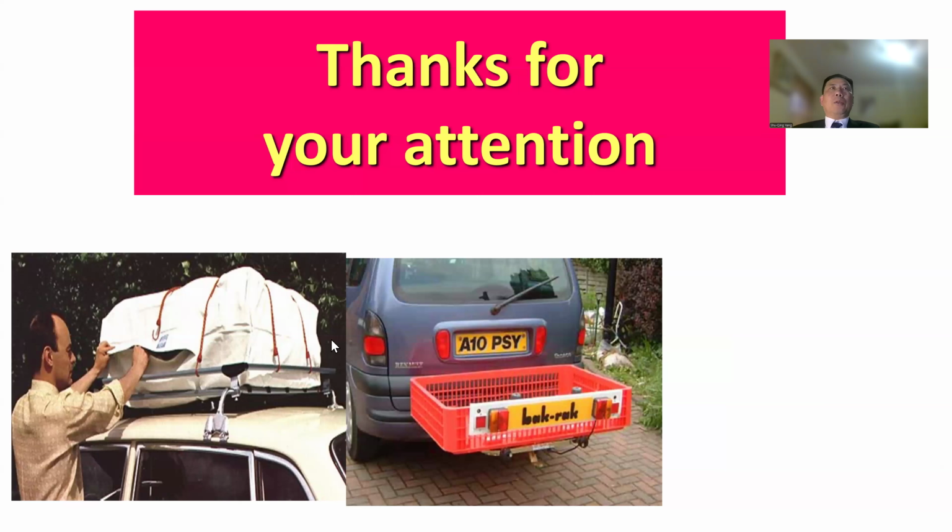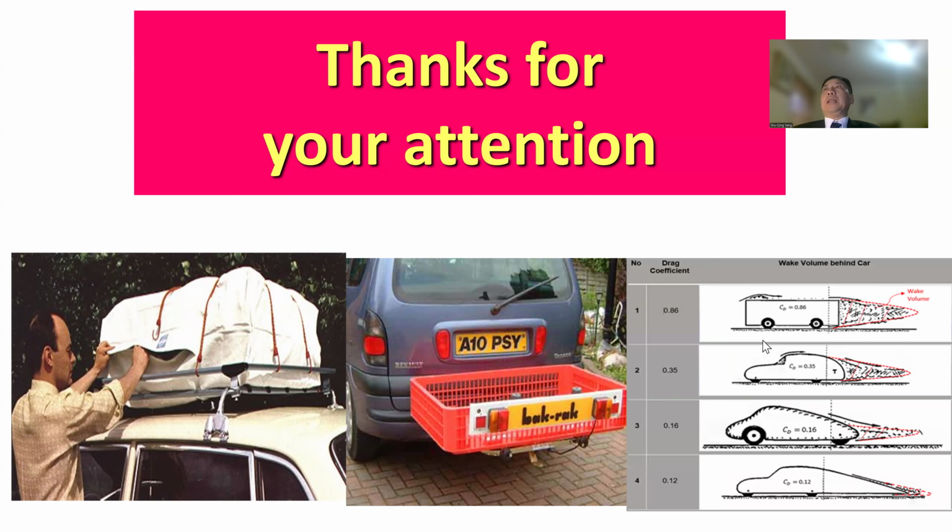And then I recommend you do an experiment for your next holiday travel. At the beginning, from your home to your destination, you put your luggage here and you count how much money you pay at the gas station. And when you come back, you move your luggage from here to here. You will see your payment will be reduced. Why? Because here you have a large wake volume, and then you have a large drag force, you have more energy loss, and this will be reduced one by one.